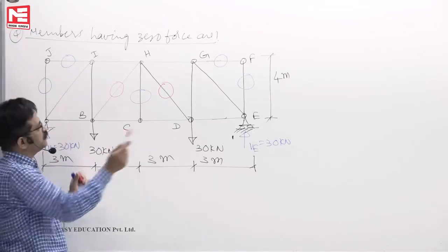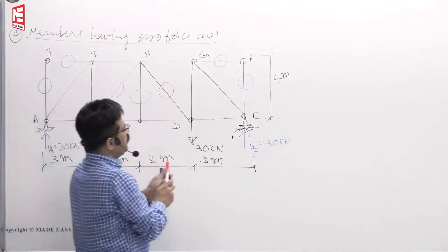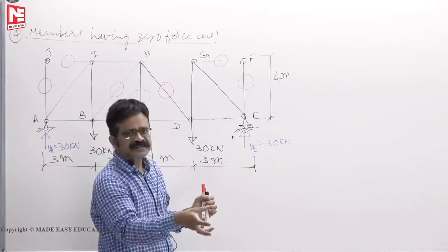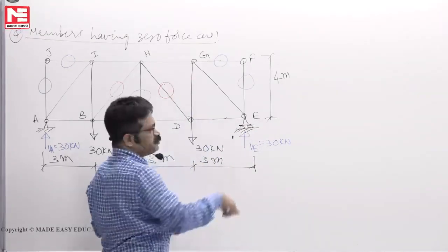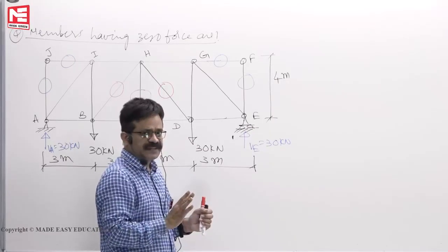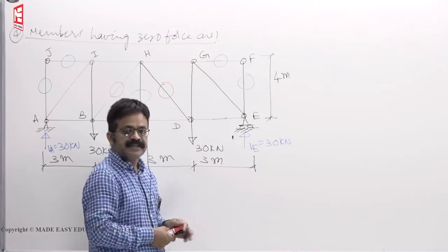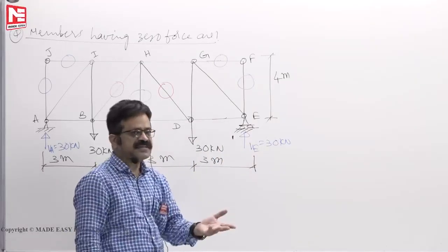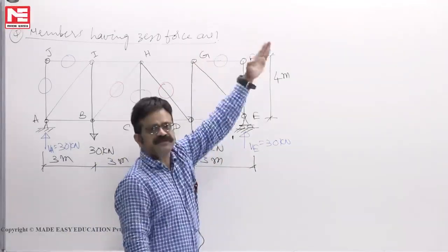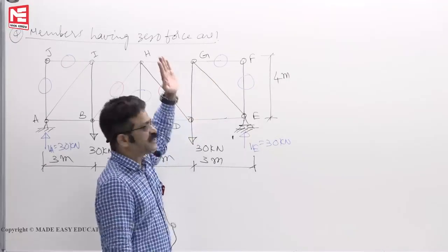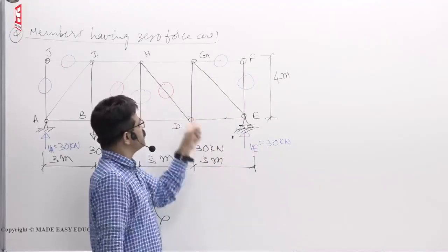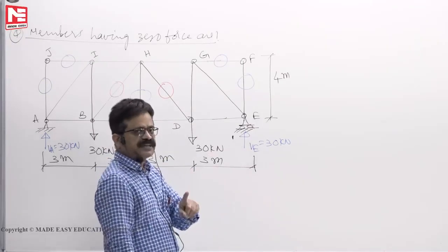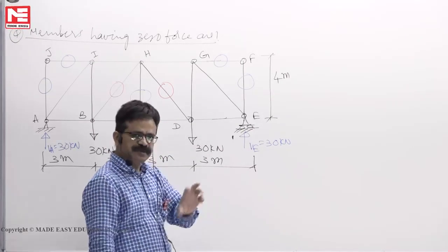That's all. So, you see, for each panel, if you draw a free body diagram, cut the beam and look at the right side or left side, you find the force in this member is not 0, this one is 0, like that. We cannot manage that in the exam. That is for beginners, cutting there and seeing how it looks. After understanding that, this is how you have to stand: stand here, look one side, and you detect whether it is 0 or not. Stand here, the sum is 0, so it has to be 0. Like that. First, you are expected to know those concepts beforehand.